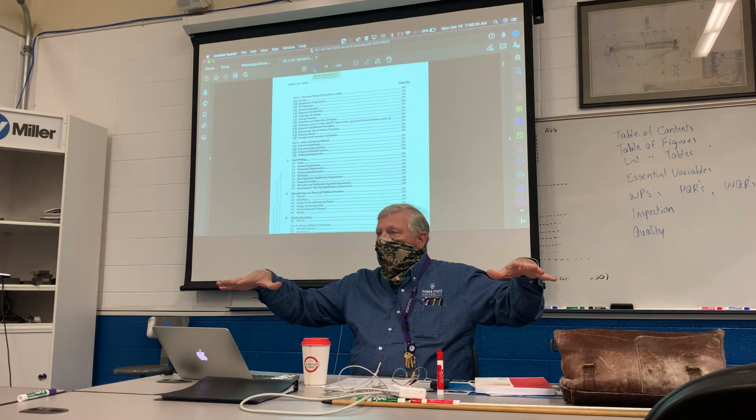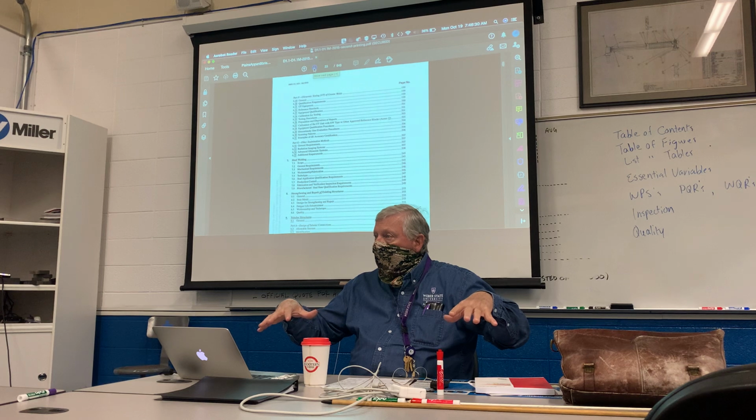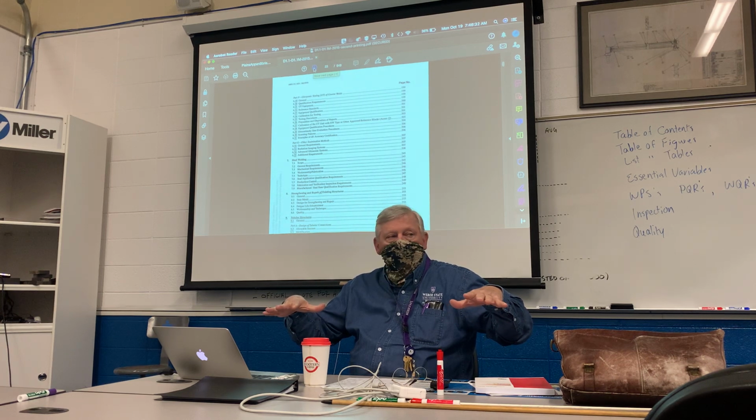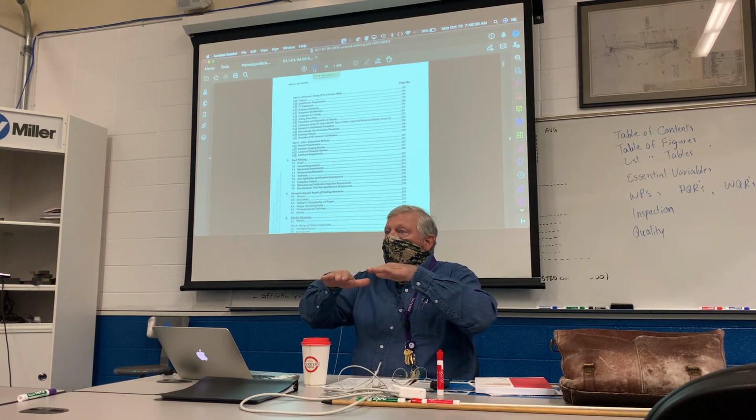They weld them onto steel structures, and then they cast concrete in this area. What do the studs do? Hold the concrete to the steel? No, that's not the main reason for studs, and this is something you'll learn today. The placement and the number of those studs is to create a shear plane.